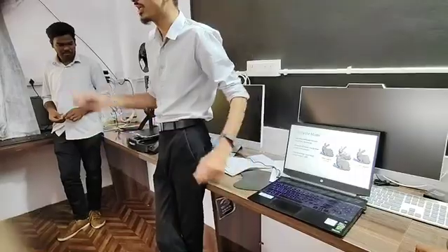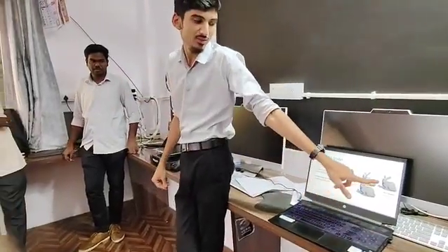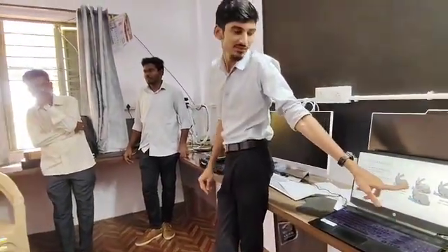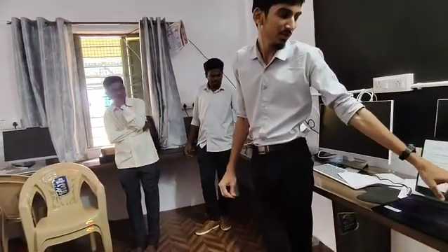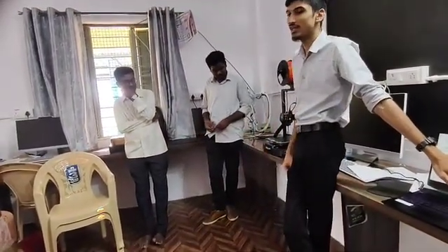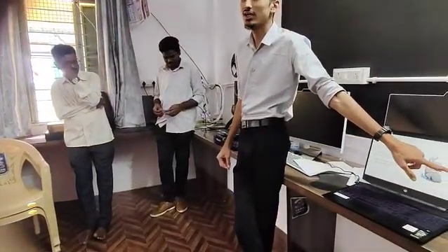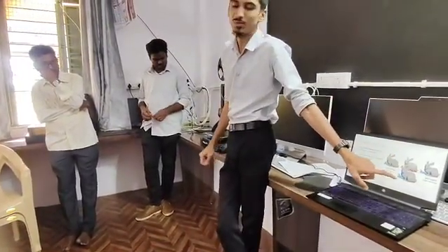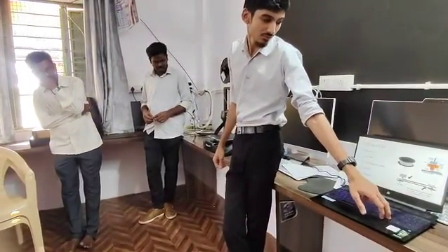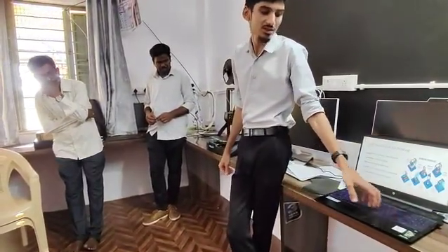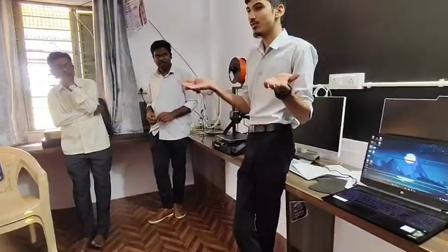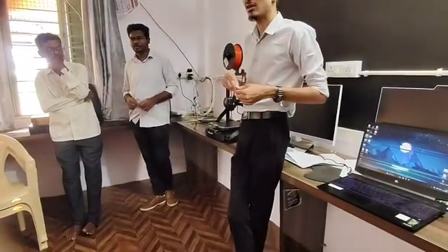So depending on how big your layer is, you get a more detailed 3D model, or you can get a rough 3D model where you can see the 3D model is there but with rough lines. The thinner your lines are, the higher the quality, but the more time it takes to print. And I will explain this. Other than that, you have to come here and see how it actually works.